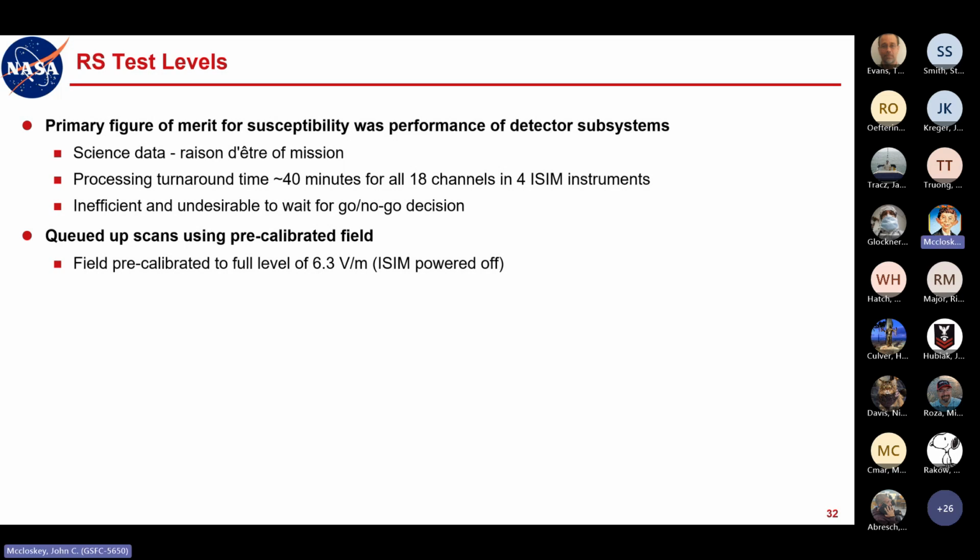And we did some characterization tests to compare. If we apply an equivalent field of 2 volts per meter, what's the equivalent at cryogenic temperatures? We had a detector operating in a Dewar, and we actually used CS114 to do this. With an equivalent level of 2 volts per meter, what level do we have to apply at room temperature to get the same level of interference?